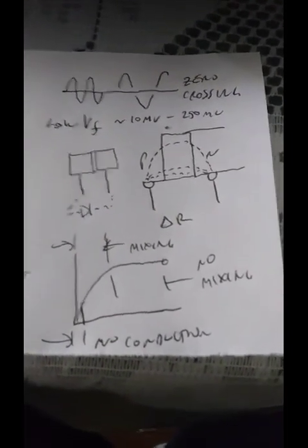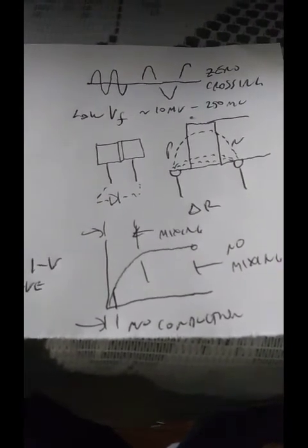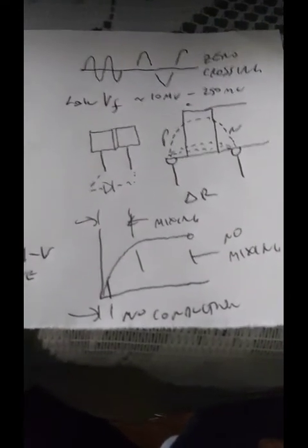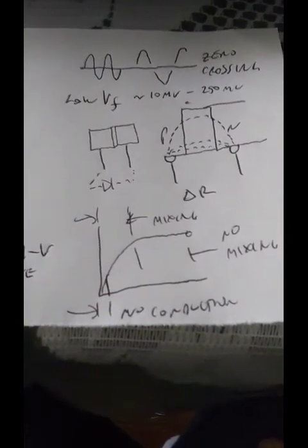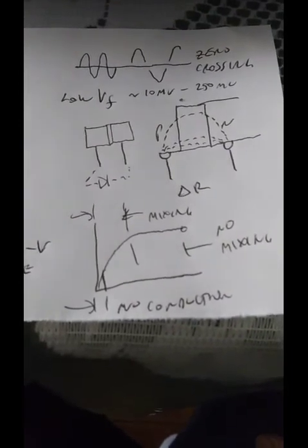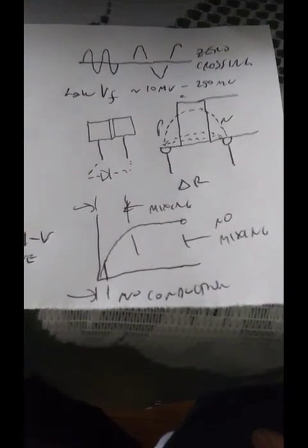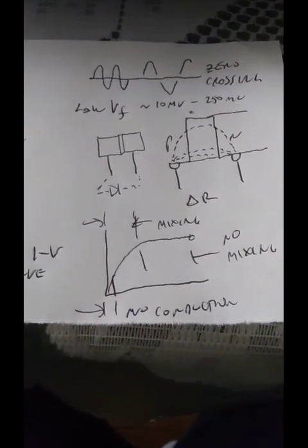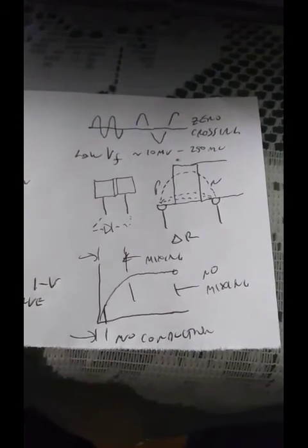The mixing range of the diode must be sufficient to allow sufficient carrier throughput and sufficient modulation throughput to put enough signal out of the sideband filter into the mixer to be able to generate enough signal downstream to the PA driver and to drive the PA stage to full conduction. Otherwise, the power output from the transmitter will drop. So this is rather complicated and difficult to measure and really difficult to do on paper.